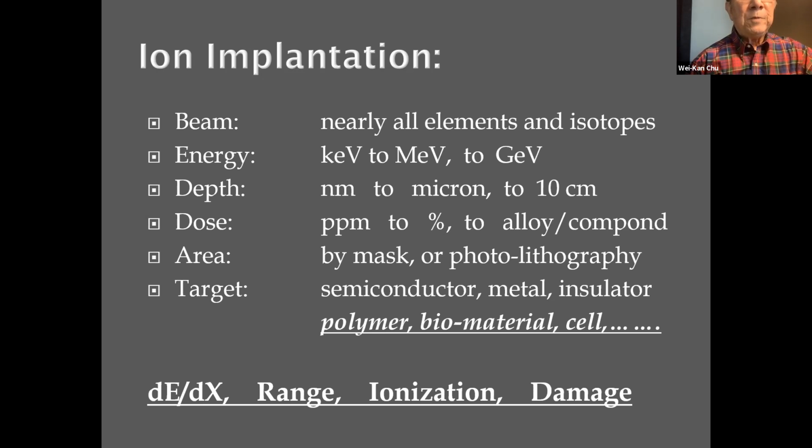Therefore, keV implantation turns out to be important because you want to make the dopant very, very shallow. As the device gets smaller and smaller, when you're smaller in area, you also want to be smaller in depth. Therefore, you make a three-dimensional, very tiny device. So keV implantation is as important as MeV.